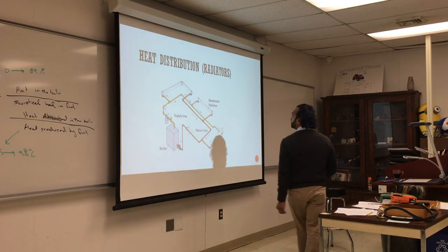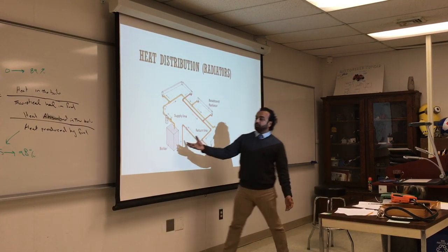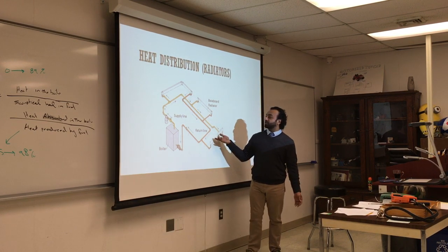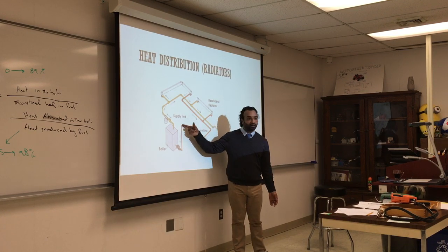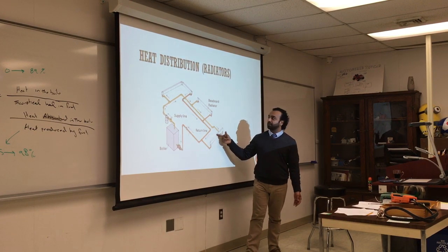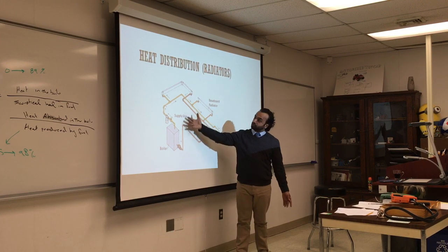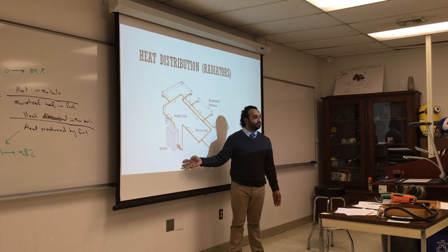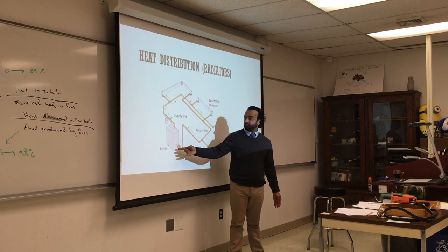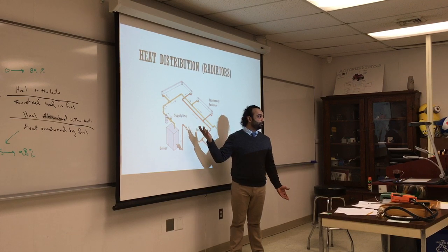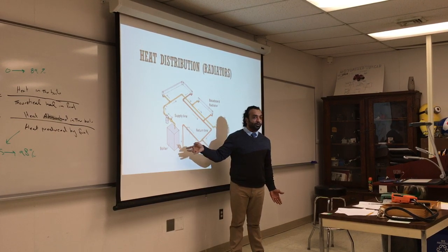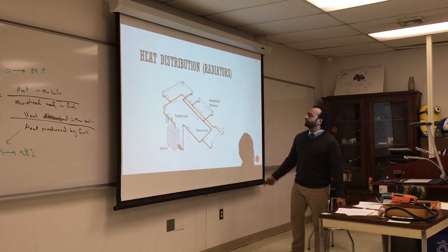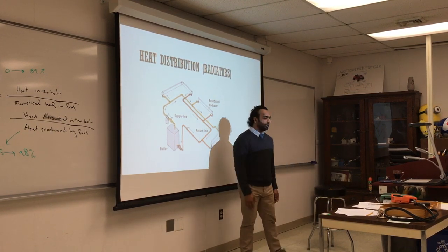So let's think about this efficiency. Let's say we made on average 85% in here. By the time it gets to your room and distributed, we've got to lose some in here, right? Yeah, it could be 5% in here, and some over here. So that's also, again, the system efficiency. This is up to you on how much insulation you have on the pipes. Eventually you will lose some, but some of it you cannot do without. No matter how much insulation you put, you're still going to lose some. So you have to account for that, depending on those radiators and how fast they give you hot air coming out.